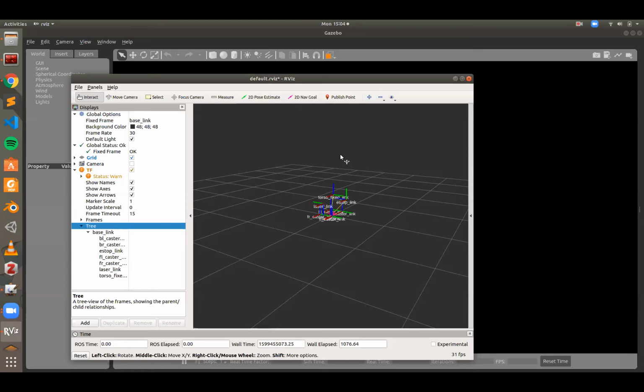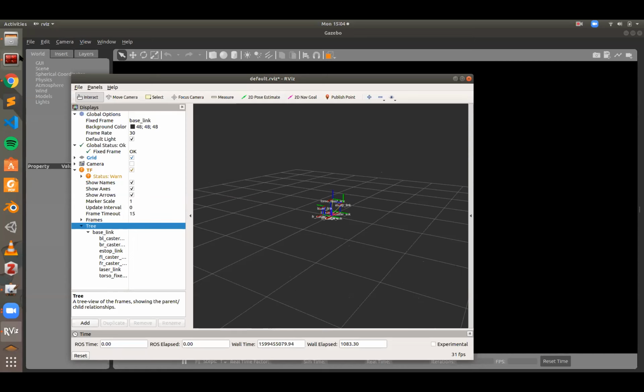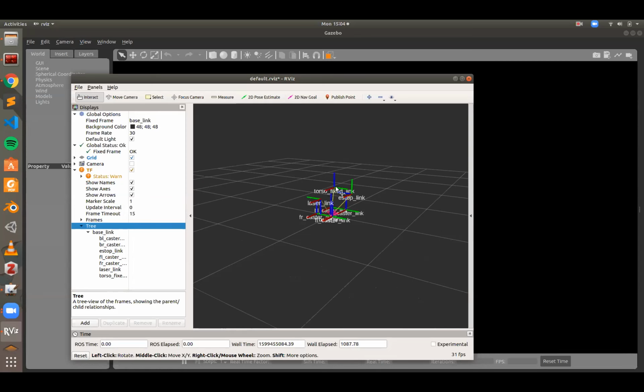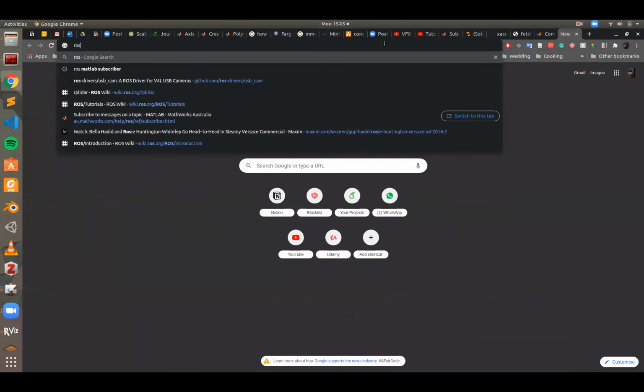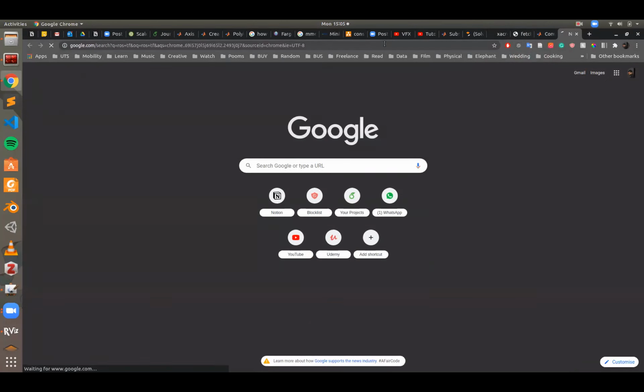Yeah, because I should get the camera frames and everything up here as well. I'll figure that out, and we'll continue this discussion next week. But just remember, the TF is a very important thing because it will show you all the different coordinate frames in action. For example, if you're getting images from a camera, it will be coming in the camera coordinate frame, and then you'll have to transform it from the camera coordinate frame to the base one, right? So everything about ROS transformations can be found if you just Google ROS TF, right?